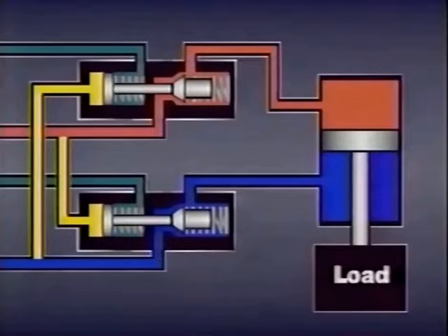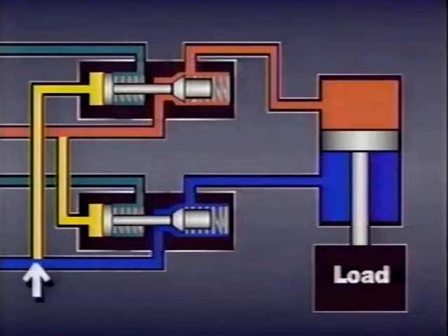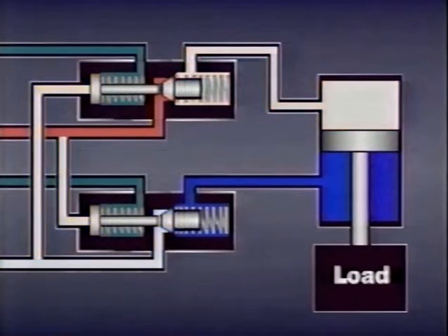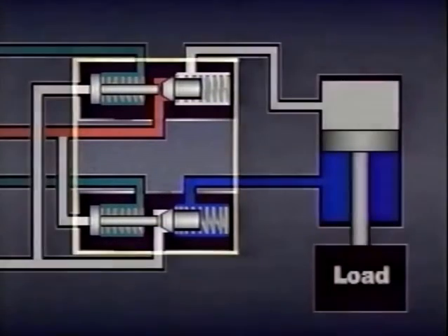In some instances, it's necessary to stop a load in place so it won't move either way. To do this, we can install two pilot-operated check valves. Each line into the cylinder provides pilot pressure that keeps a check valve on the opposite line open, so fluid can flow in both directions. However, when pilot pressure is removed, both valves reseat, and the load may be locked in place.